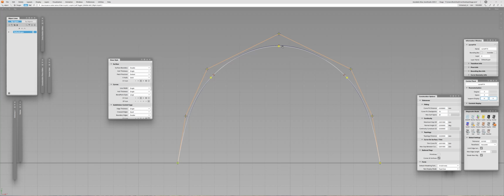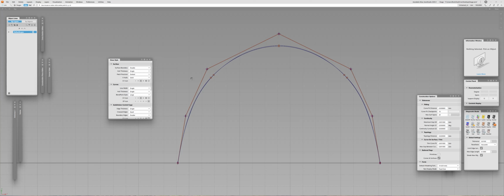So when you create the curve, be sure that you are in uniform, and it will eliminate some pain when you try to adjust two curves together, and these curves are multi-span. And one important note: this chordal and uniform distinction is only true when you have a non-uniform knot vector. So if the knot vector is uniform, so there is only one span, it doesn't matter which one you pick. It will work identically. It will make differences only when you have more than one span. And I believe that's important to mention.